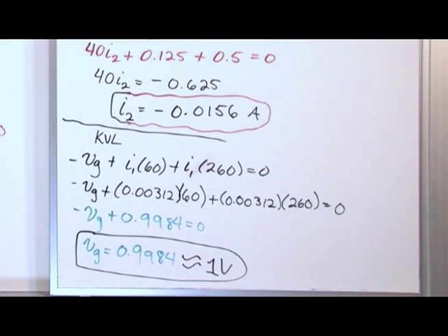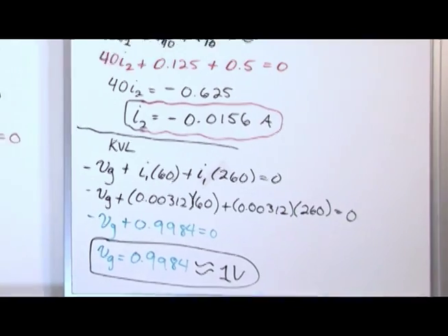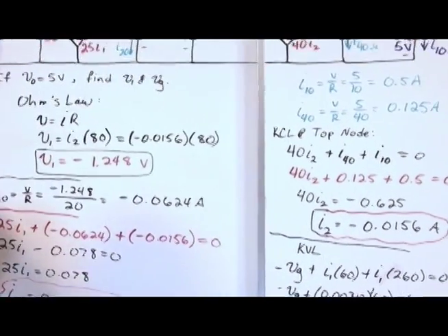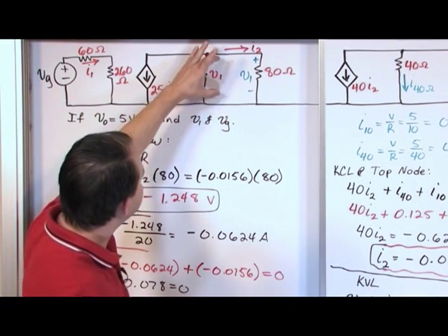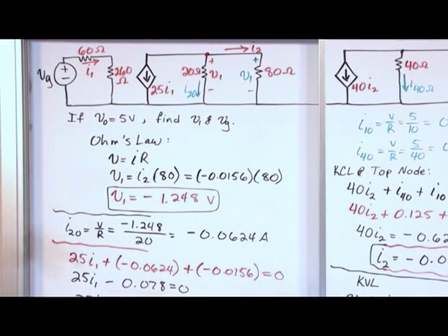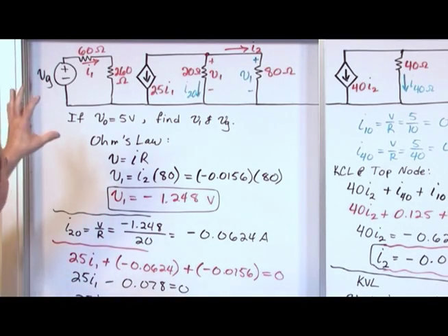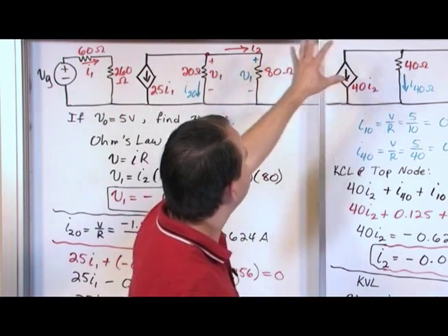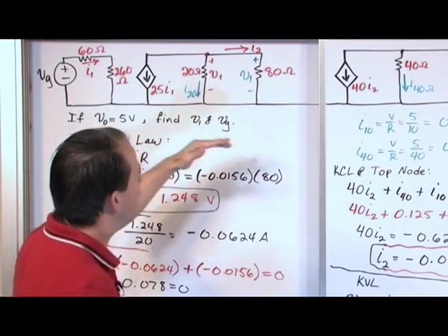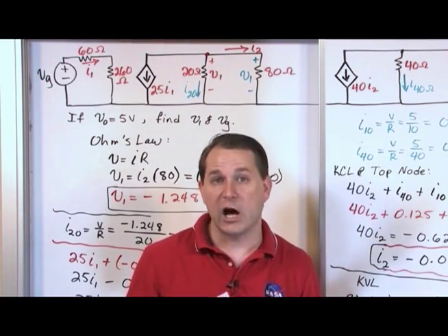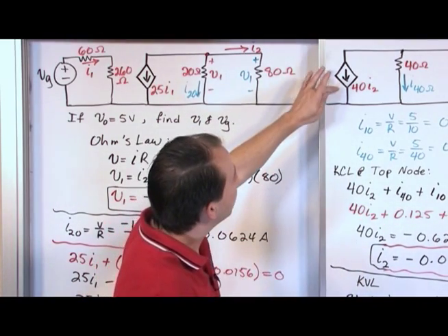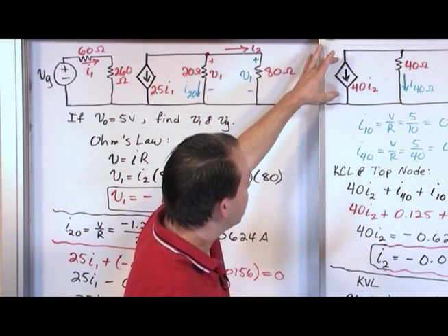So there you go. What we have found from this is the source voltage is actually just a 1 volt source. And the voltage across these resistors here, which was the other thing we were trying to find, is given by this. So let's go through it really quickly. We have this situation where we almost have like 3 separate circuits. They have a common ground, which just means the common reference for the bottom of their voltage is a common point. Because don't forget, this is a current source, but there's a voltage across it, right?